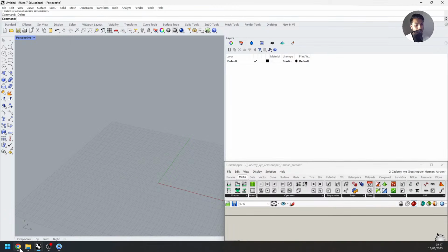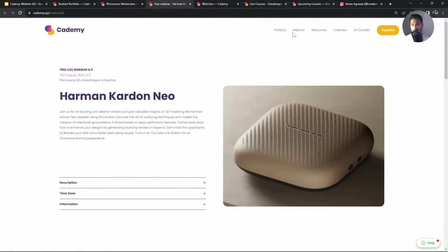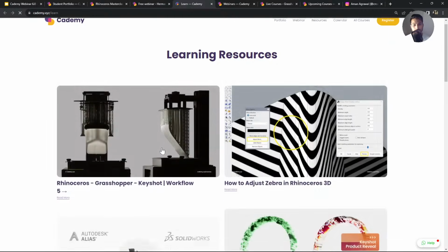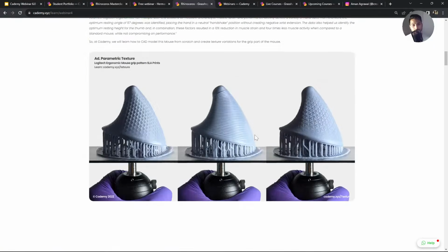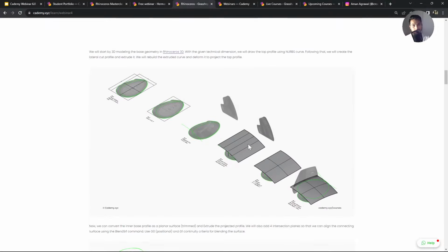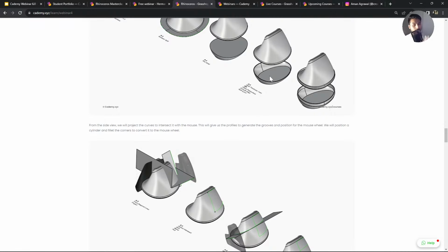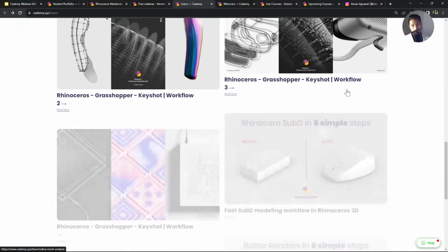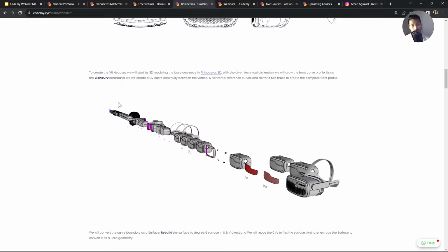But in my case, whenever I have to model a complex geometry, I model it in a step-by-step format, so that whenever I mess up something, I can go back to the previous steps and recover the geometry from there. Yes, it makes the file a bit heavier, but in the long run it saves me a lot of unnecessary challenges.